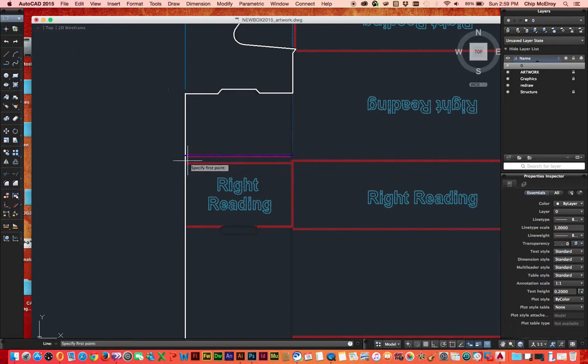And now I'm going to go in and I'm going to create each of my lines so you can see what I'm doing here. So let's go in and I'm going to create each one of my lines here. So let's drag this one. So let's get that placed, and we know that this is a panel fold. So I'm going to go in here and create each one of these. And even though that's a die punch, I'm going to go ahead just short of the die punch. Click that, hit my space bar to release it.